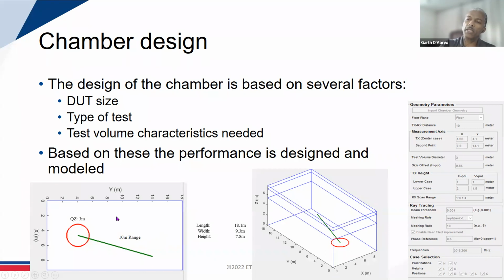So if you know that with a particular position of antenna and quiet zone, most of the energy will arrive in your quiet zone as a result of a single reflection at the half angle of this path, then it means that you're going to need more absorber or better performance in this area, but you can probably get away with less absorption in some other area, because for energy to arrive at this area from this wall, it must interact with other surfaces. So you have the benefit of multiple reflections or multiple absorption events before it arrives here. It just allows you to optimize the layout of the absorbers.